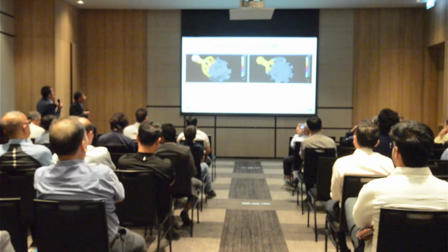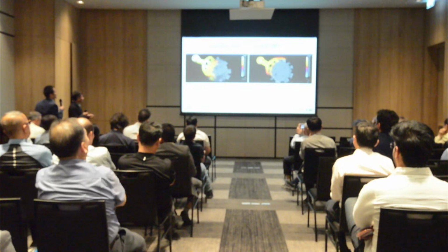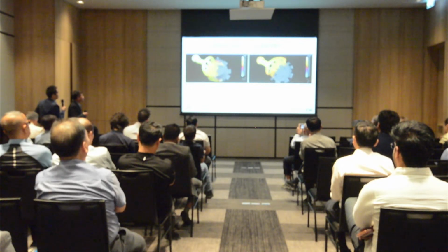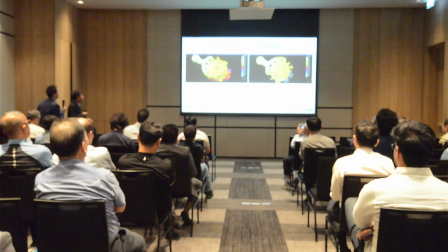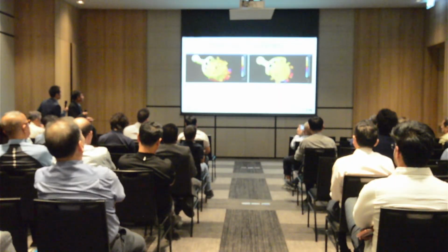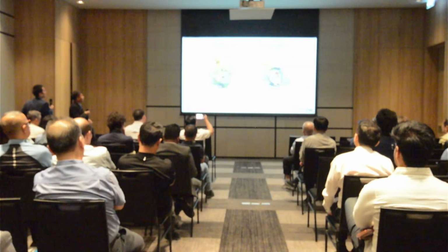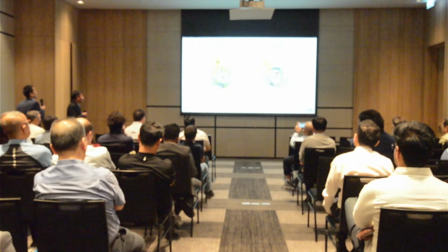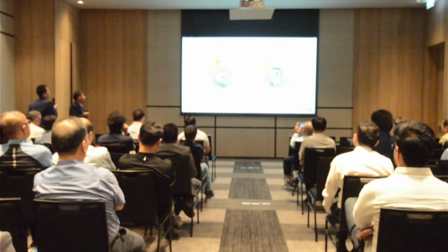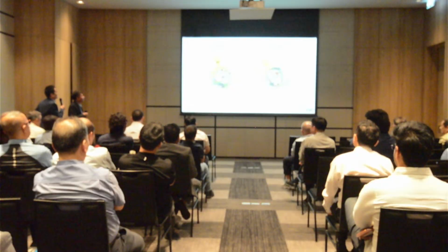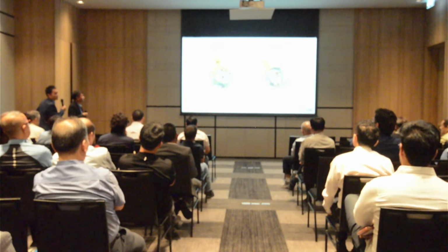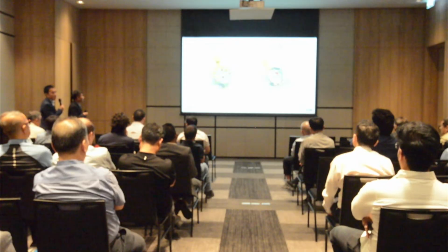This is the thermal simulation, the temperature distribution. Based on the hotspot area, we design the final thermal balance and the cooling channels to get a uniform mold temperature.